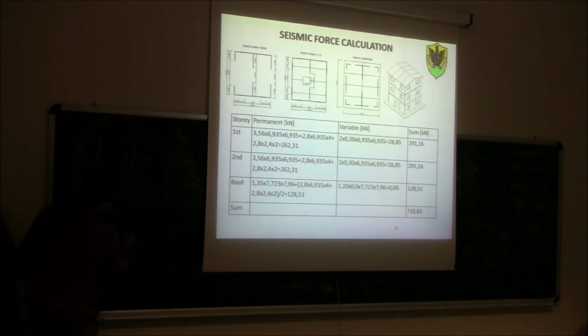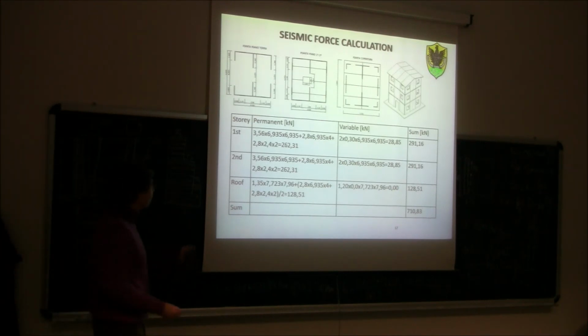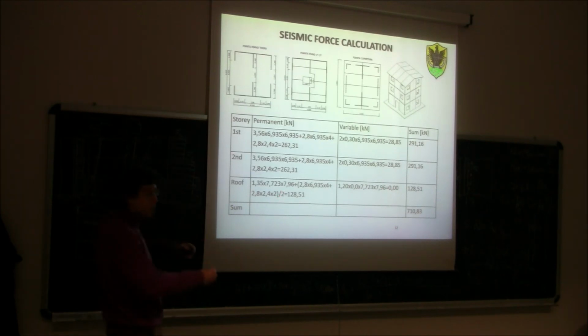So in the end, I can consider the total height of the wall. Same thing here, half and half. But of course, on a roof, I have only half the weight of the wall underneath the roof, because I don't have anything above the roof. So for the roof, the quantity inside the bracket has to be divided by 2, because I have only the half below, I don't have anything above.